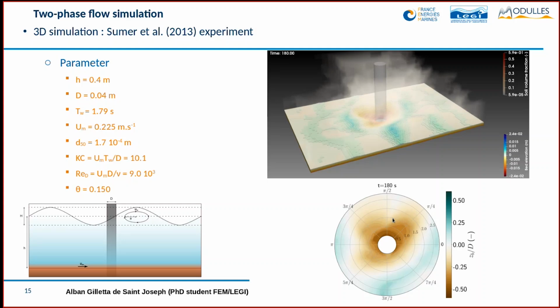At the end of the simulations, you have a very intense plume in the suspended load, as you can see on the top figure, with a white plume very intense in the water column. And downstream, you can see that the scour equilibrium is not totally symmetric, because different physical processes took place during this wave flow.